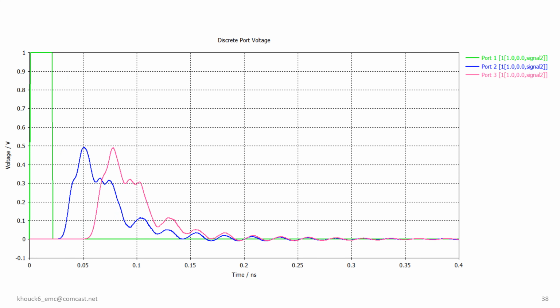In this illustration, the propagation of a signal originating at port 1 along the trace and past port 2 and port 3 is depicted. However, the signal experiences significant attenuation and elongation of its period along this path. This degradation in signal quality is attributed to the reference transition occurring from the pin of the device to the reference plane situated beneath the trace.